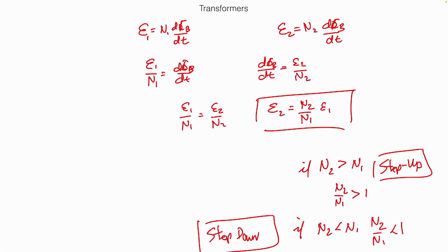It's voltage, right? So we have a way in a transformer, which is the physical manifestation of Faraday's law of electromagnetic induction, to change voltage on the fly. If I need more voltage, I just put more windings in my secondary than I have in my primary. And I can tune it to whatever voltage I want, right? If I know I need 5 volts out and I'm doing 115 volts in, that's going to be a very specific ratio of windings that I need to make that happen.